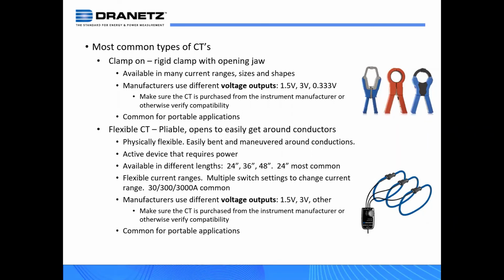So if you have the ability, again, the instrumentation has the ability that during the voltage transient, where did it originate from? Was it upstream of the monitoring location? Was it downstream? And if you have the proper current probe that has the bandwidth, and you have the instrumentation that is capable of recording current transients, then you can use that same relationship to determine the origin of the transient itself.